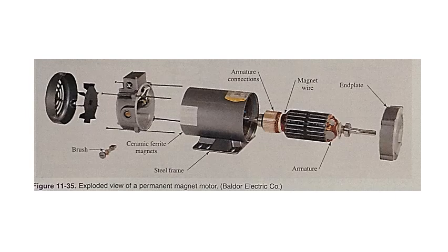DC servo motor. A servo motor is any motor that is modified to give feedback information concerning the motor's speed, direction of rotation, and sometimes the number of revolutions it has made. This feedback is used to determine position of the mechanism it is driving, such as a robotic arm.